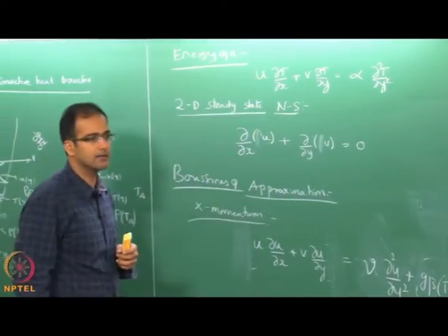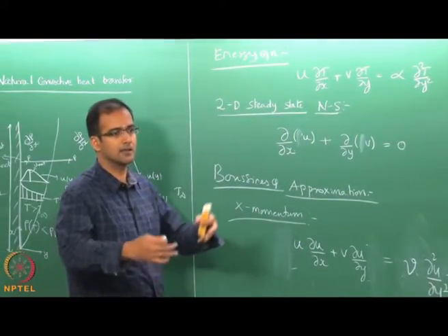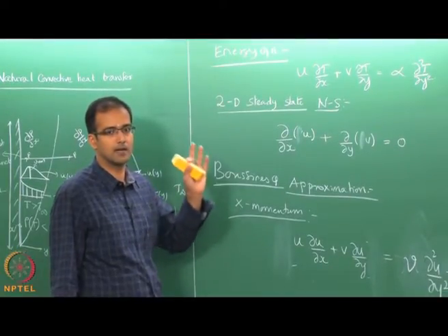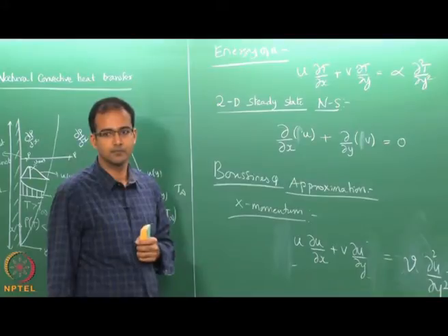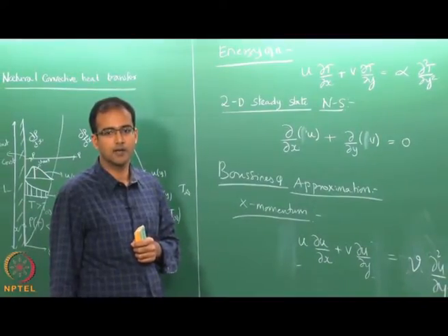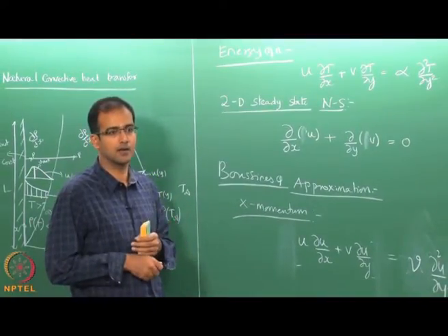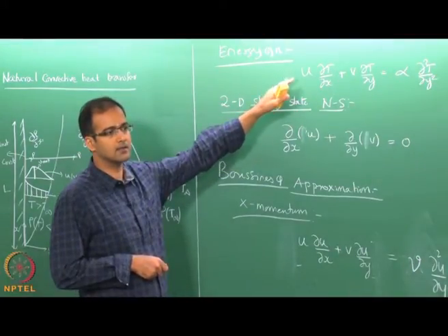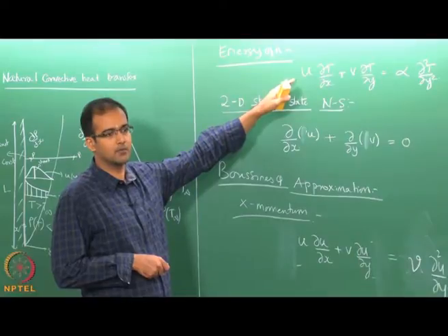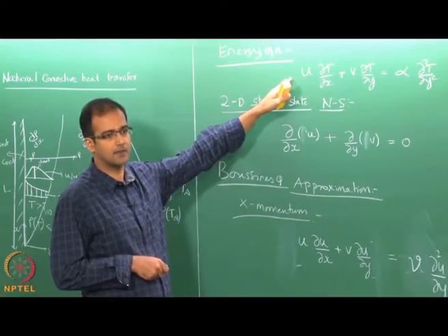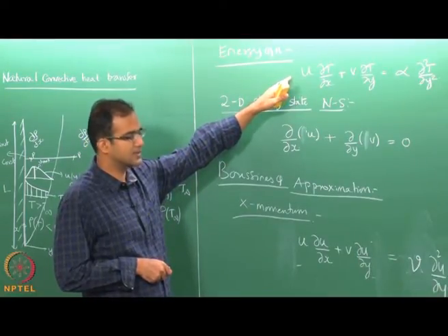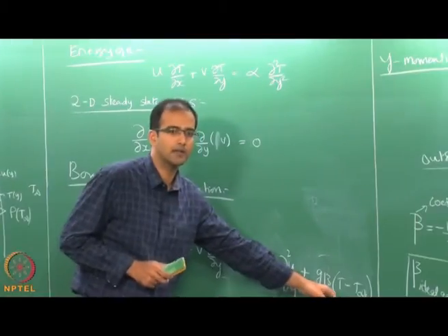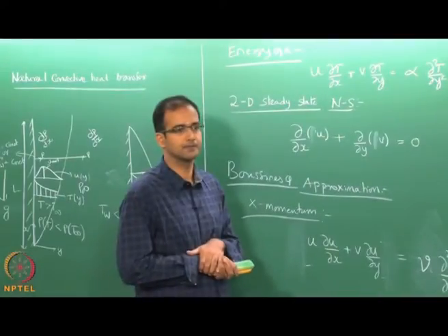You can neglect heat diffusion in the x direction with respect to y, and also neglect viscous dissipation, since we are talking about small values of Eckert numbers. In that case this will be the same as external laminar forced convection past a flat plate. So, this will not change. The major difference is the inclusion of the buoyancy term in the momentum equation.